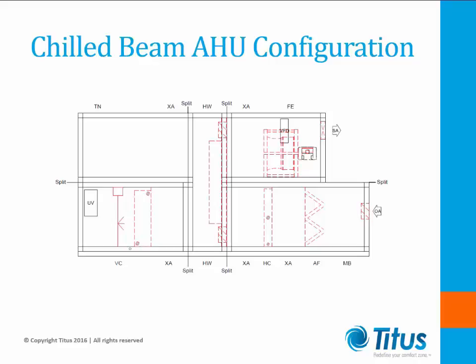The energy expended for the additional dehumidification will be minimal, along with the pressure drop across the wheel and the energy to turn it. The coil must be sized to maximize latent capacity, or another way of saying it is to minimize sensible heat ratio. This can be accomplished by deeper coils moving air at decreased velocities, and the deeper coil at a lower velocity allows the air to stay in contact with the cooling surface longer, which allows more water to condense out of the air stream and thus increase the latent capacity of the coil.